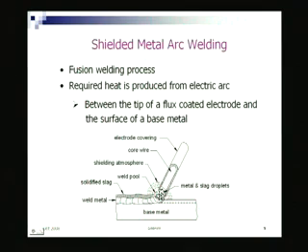because when you have the electrode, it is not touching the metal, there is a gap. Through this gap the molten metal is getting transferred, the electrode tip is melting and getting transferred. While getting transferred, it could get oxidized, because there it is not protected by the slag. Slag is only above the molten pool.